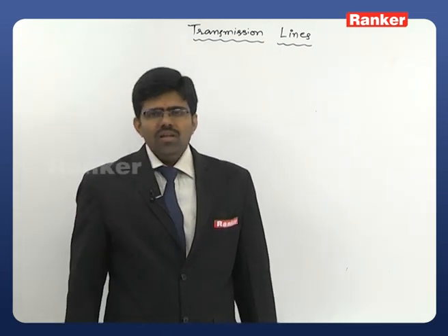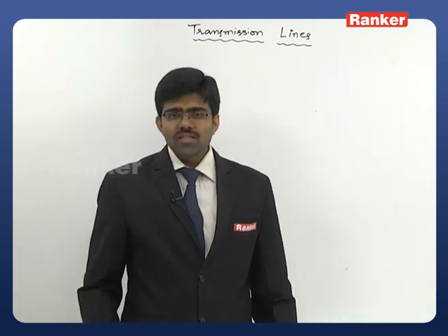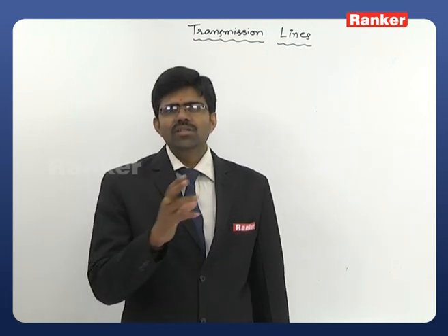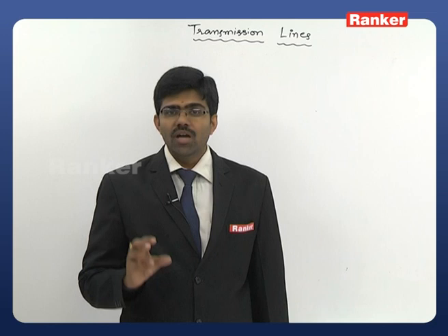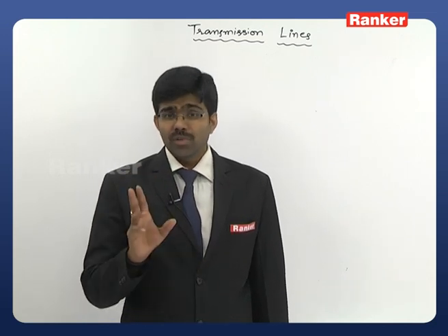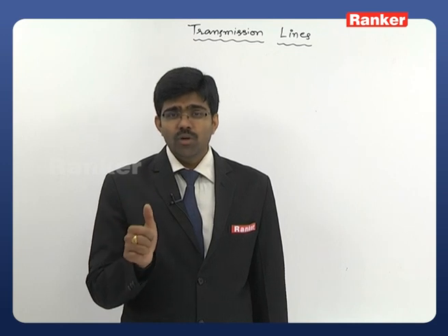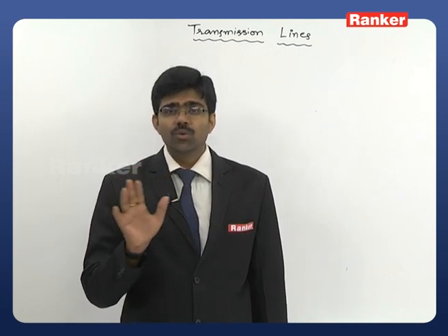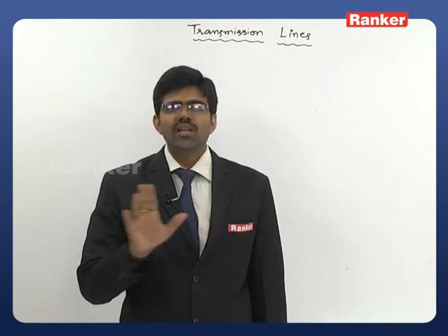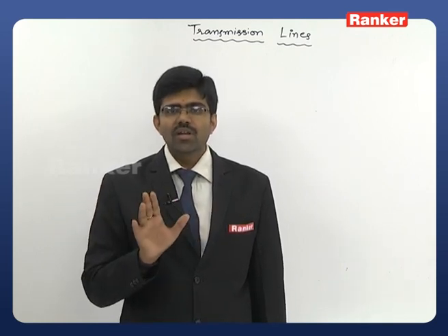Now a very interesting point: what is the relation between all these things? We represented our transmission line with the combination of RLGC, but there is a unique relation between all these things, and we need to remember them. The first and very important point is that it is a clearly distributed structure. The entire RLGC is distributed over the transmission line; they are not at all lumped or discrete.